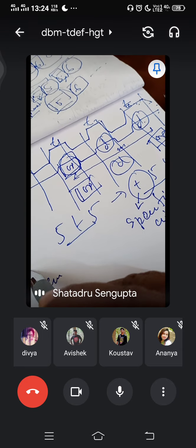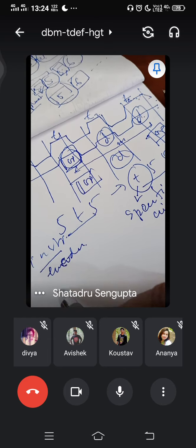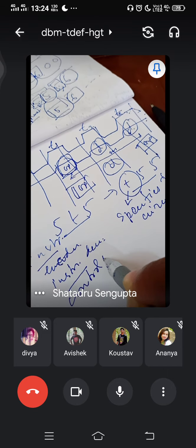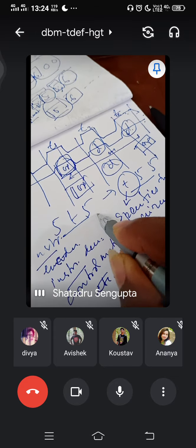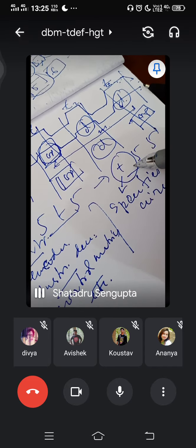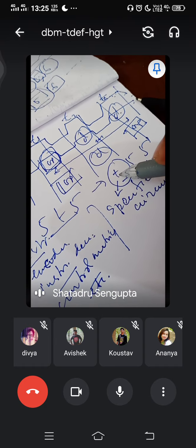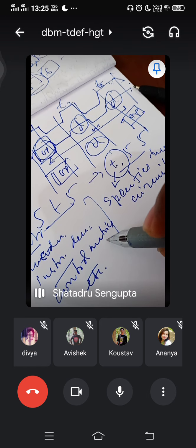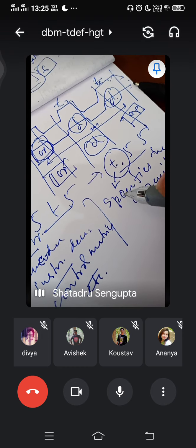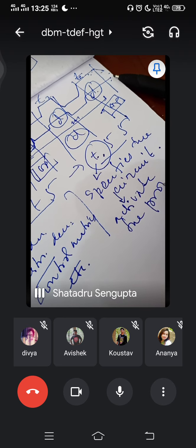There is the instruction encoder, there is the instruction decoder, there are the control matrices, etc. Through a combination of these, whatever circuit is to be used, the opcode for this is recognized because it is coming in the first clock pulse of the machine cycle, recognized as an instruction, goes through the instruction decoder, and through the control matrix, or it may just be through the control matrix, whatever is the case, it will just activate the proper circuit.